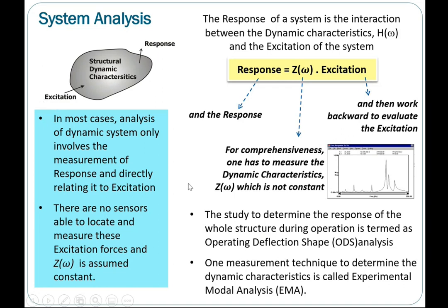A lot of the time, you cannot measure the force. On your running system or in-service machines, you do not know how much force is actually created at that particular point. So what we need to do is measure the response at that particular point, which is vibration, using the sensors that you have learned earlier.